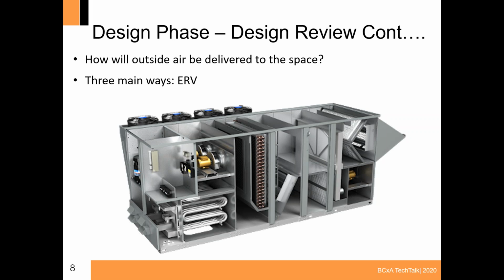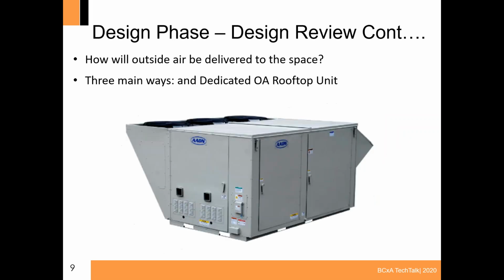Another issue is that they're also very complex units, so some field installers and programmers may not understand how to successfully set up the unit. There is potential for cross-contamination through the energy wheel, but usually it is negligible. The last method I see is the dedicated outside air rooftop, and some advantages to this are they're simpler and they avoid cross-contamination.